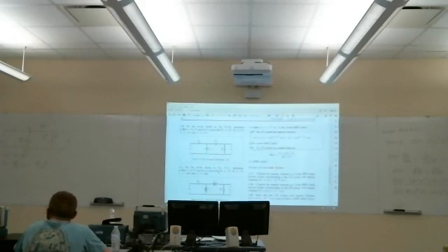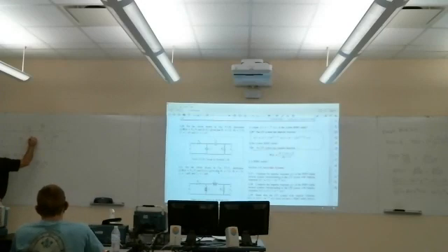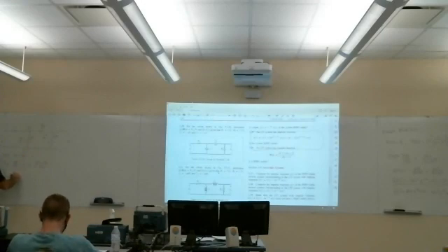Now, I said you can let these voltages be anything. You can't let them be 0, right? Because then the input voltage would be 0, and that ratio doesn't exist. But any non-zero value that's convenient. Okay, so let's call this Ix. Ix would be Vx divided by the impedance of that cap. It's going to be s over 10 to the 6, so my s's actually cancel out.